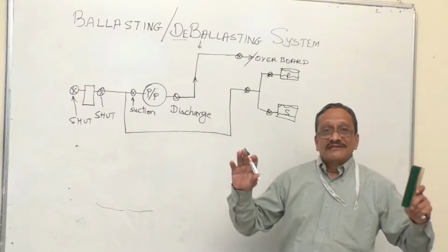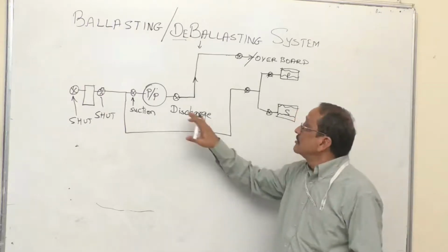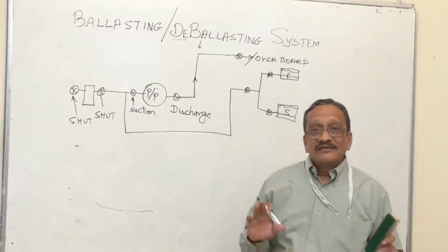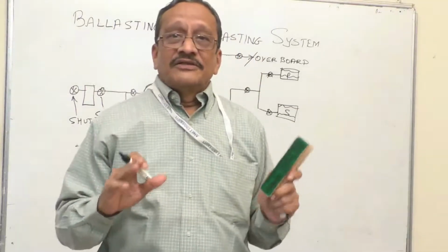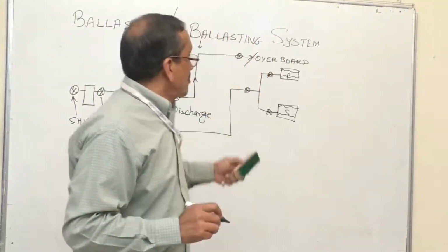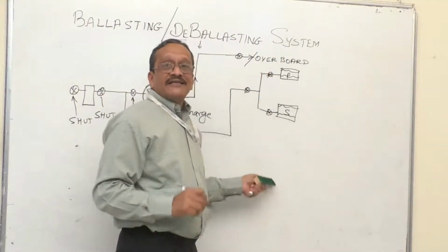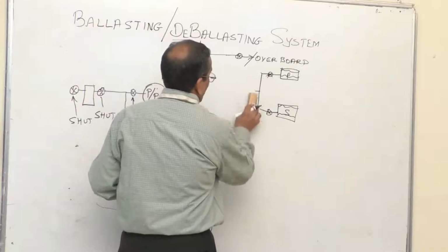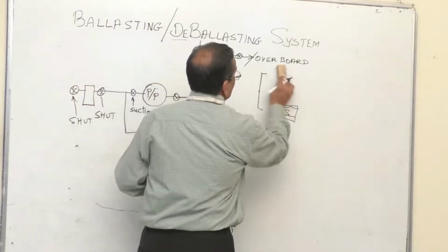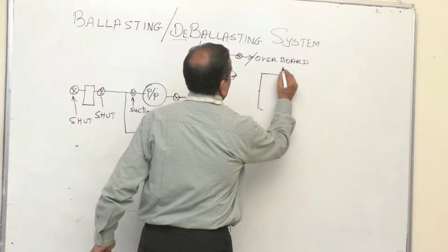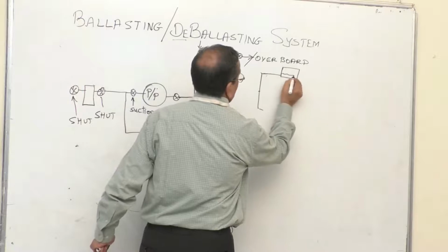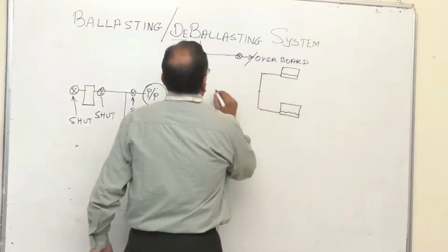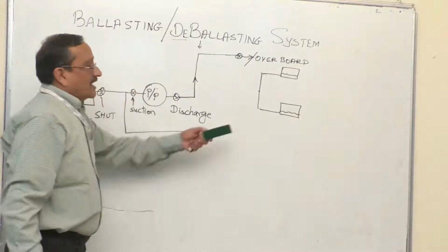So I have to ensure that that quantity of water is also getting pumped out. But please understand, the pump is not taking suction. So here, there is another arrangement for the tanks to be stripped. So that is called stripping. So whatever little water that is there inside the tank, that can be stripped. And how do we do that? So just modify this diagram again. So whatever little quantity of water that is available over here has to be pumped out.